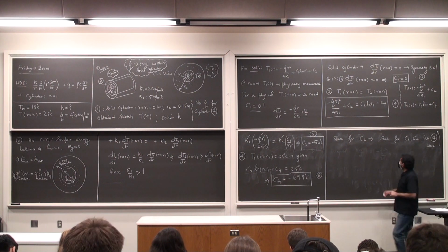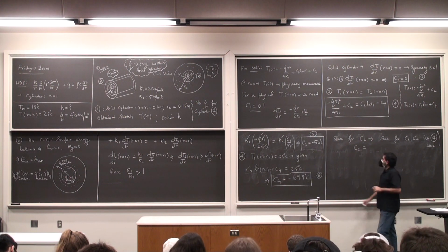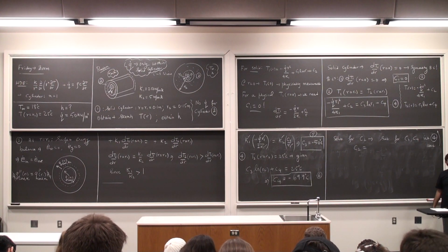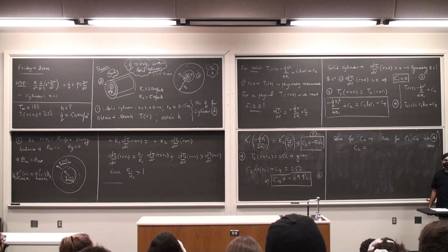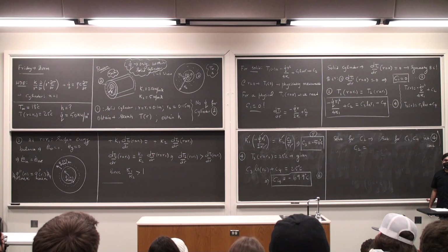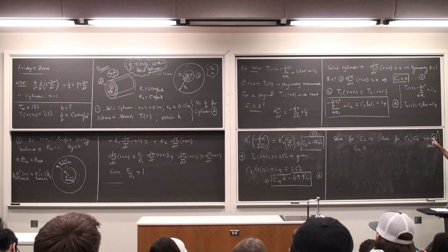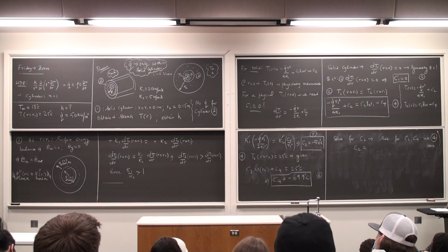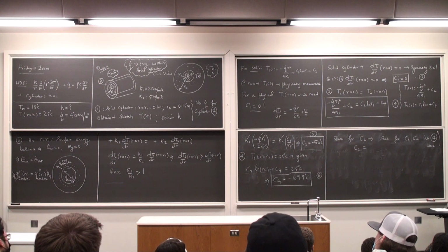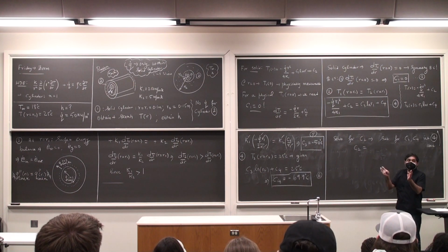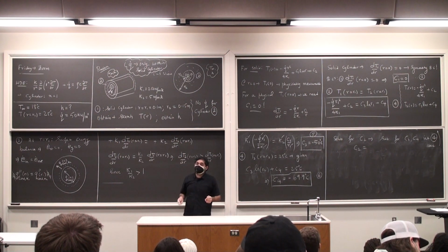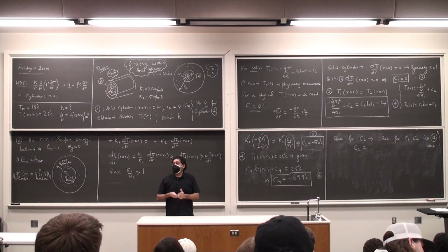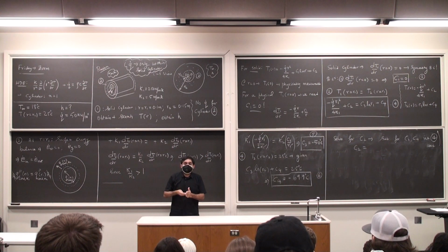So C2, should C2 be positive or negative without solving for anything? Just by looking at that equation, you don't even need to look at the values, just imagine you have a solid cylinder. The outer ring at R2 is at a temperature of 25 degrees, the ambient is 18 degrees, heat transfer is taking place from the solid ring onto the shell and then onto the ambient. So what should the temperature at the center line be? Is it positive or negative? Has to be positive, physically speaking.